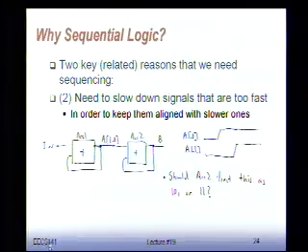Now I have two independent waveforms, and I don't know exactly when they're both going to be valid. So again, should it be 1, 0? Is this 1, 1? We don't really know. A time base helps us align the different signals together in the chip. It basically tells you, at this point in time, both of them are valid, and we can go on to the next step.